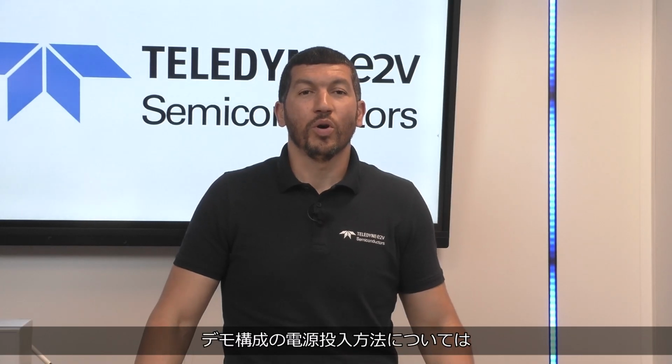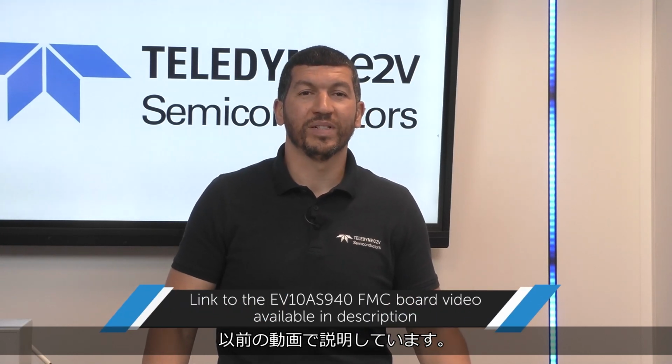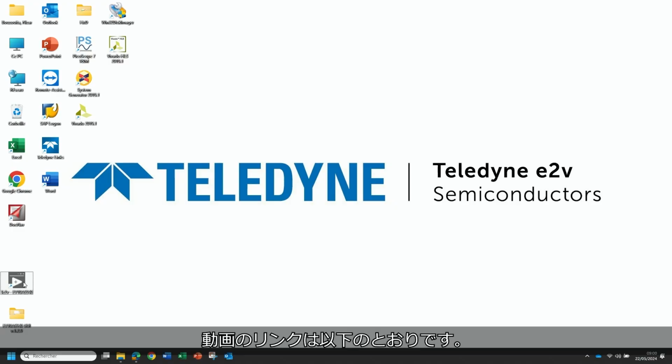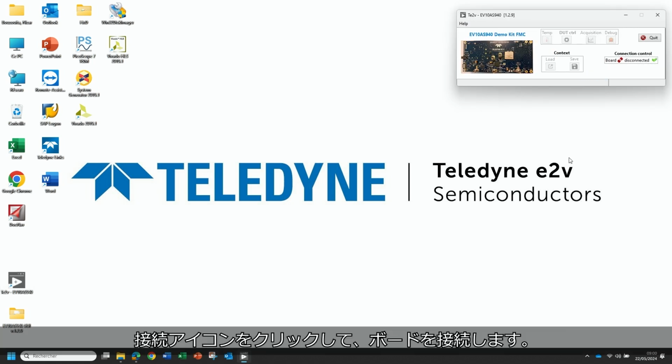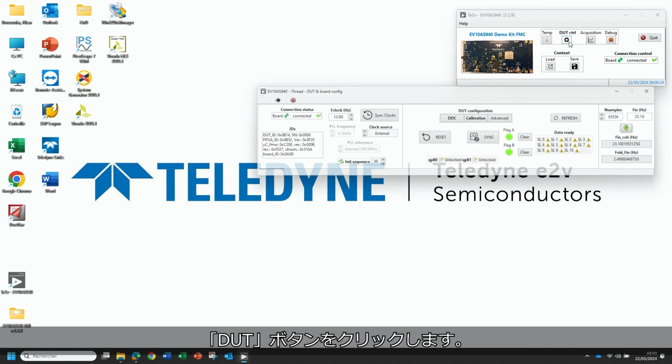The powering up of the bench is not part of this tutorial and was explained in a previous video. You will find the link for the video below. After powering up, launch the GUI. Click on the connect icon to connect the board. Check that the socket icon turns green. This indicates that the AS940 board is detected. Click on the DUT button.